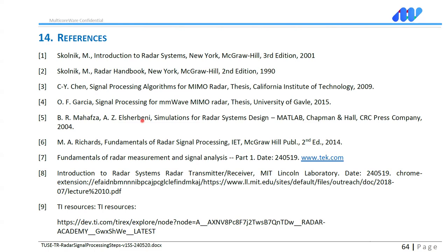So your peak is going to go up. But the problem is, if your pulse is too long, then your Doppler is not going to work. So the longer your range, the shorter your Doppler. So you need to optimize it, and that's where the parameter setting for radars comes in.